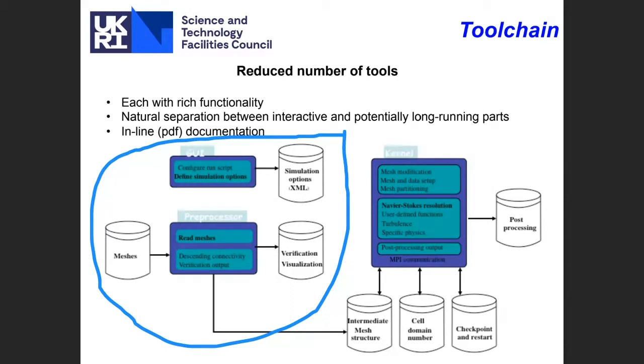That's where the UNV file you had yesterday was converted into a format that Code Saturne could read, creating the mesh_input.csm file. This was done serially, as well as the XML file reading.